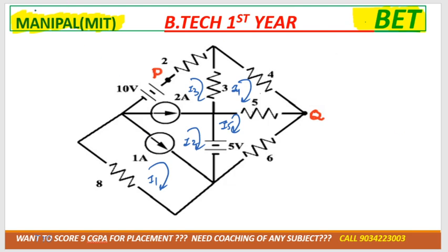Now the next question. In this we'll have 5 meshes, so we need to make 5 equations. So the question arises, ma'am, how do we start, from the mesh, from the super mesh, or from the current source? I'll suggest you start from the current source. That would be easy for you. So 1 ampere is the current source. It's in the middle branch, i1 and i2. The i1 direction is the same, so i1 would be positive, i2 would be negative. That would be equal to 1 ampere, correct?